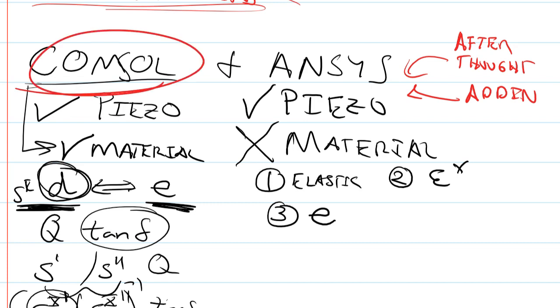In Comsol, it's not an add-in. It is part of it. It is integrated. It is just like any other solver or material type. It's not like a mechanical FEA program with piezoelectric. It is a multi-physics kind of basis. And Ansys has a long history, and that history kind of bites itself in the butt sometimes, or it becomes inconvenient, not user-friendly, awkward. But anyways, if you have a lot of experience with Ansys, then you will be able to get piezoelectric materials to work for you. But starting off the bat, choosing which platform you want to use.